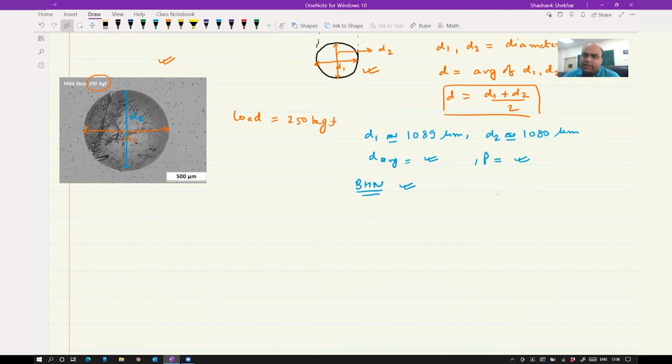In all the hardness tests, whether it is Brinell, Vickers, or Rockwell, your surface has to be smooth and you have to polish. So basically when you want to do any hardness test, you first polish your sample using conventional metallography technique, and then use either of these three indentation methods depending upon your material, and then you can calculate the hardness value. Second, it is not very suitable for thin samples because of larger indenter impression.